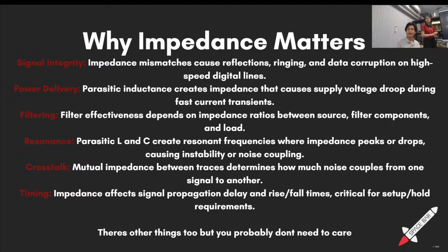Does impedance behave like resistance in a DC circuit? Yes. In DC steady state, where the DC is not changing over time, you only have resistance. If the DC is changing over time, then you will have rate of change of current and rate of change of voltage, in which case the other two components will start to appear. Basically, an inductor becomes a short circuit, and a capacitor becomes an open circuit in DC steady state conditions.